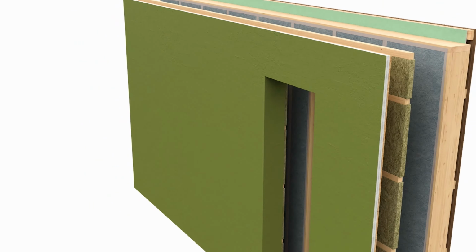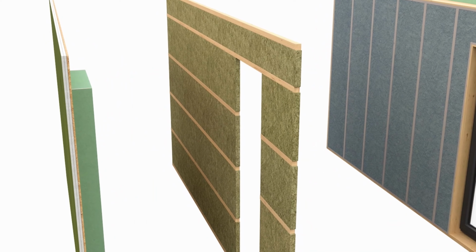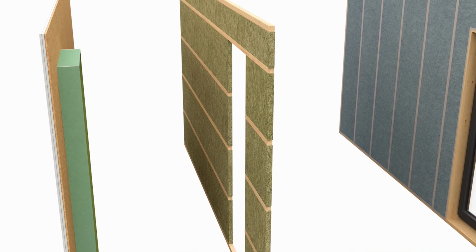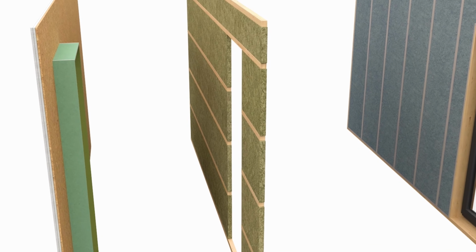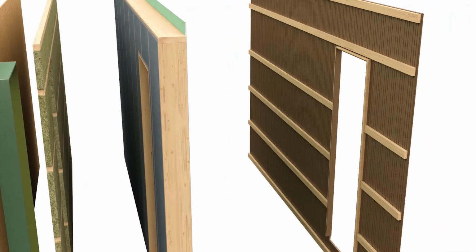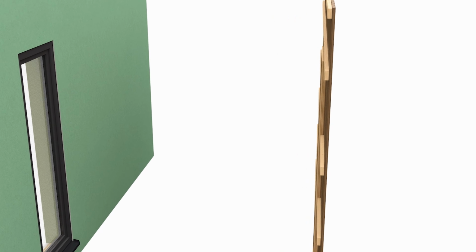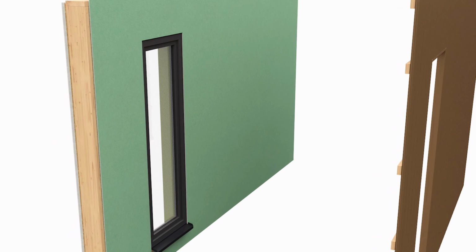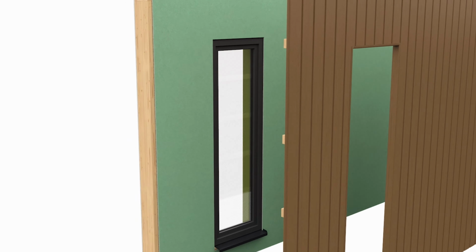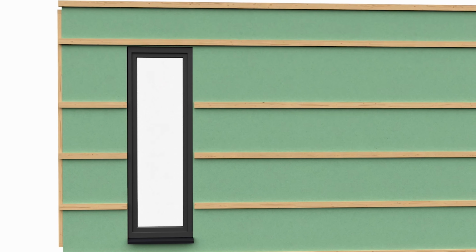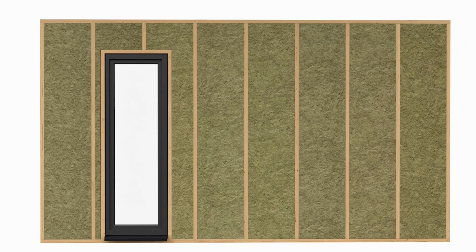Thus, the load-bearing frame may have a room-side cross-frame, which is designed to install additional insulation and create a gap for communications, like electrical cables. There may also be an external additional frame for installing additional insulation and wooden batten for fastening the cladding. The structure of the external wall also contains openings like doors and windows, for which separate spaces must be provided in the structure.